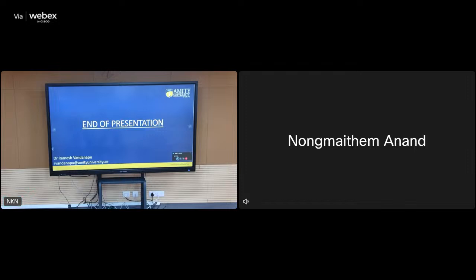Can we use pond ash as a substitute material, because it has very thin particles, and that can fill up the voids? But it has more probability to wash away also when there is an entry of water. So you make sure that entry of water has to be stopped from your side by any means. Okay, thank you.